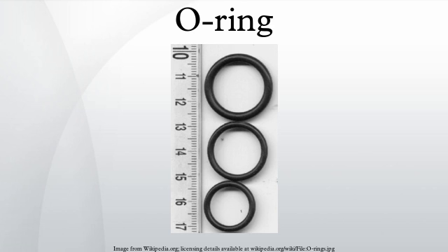During his investigation of the launch footage, Feynman observed a small outgassing event from the solid rocket booster at the joint between two segments in the moments immediately preceding the disaster. This was blamed on a failed O-ring seal. The escaping high-temperature gas impinged upon the external tank, and the entire vehicle was destroyed as a result.